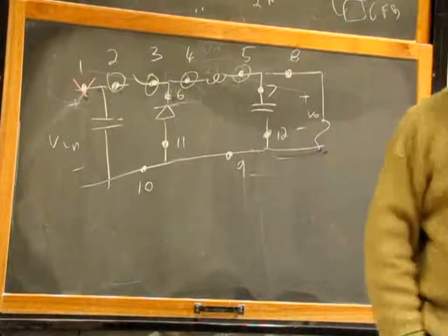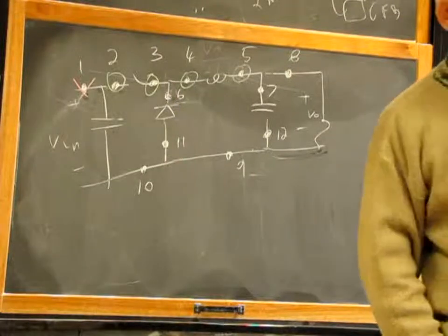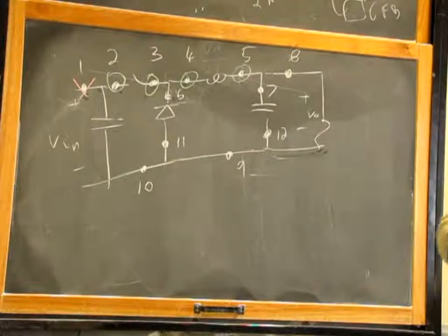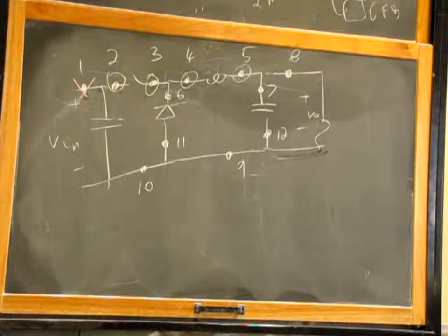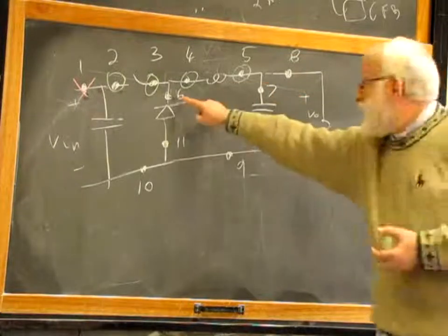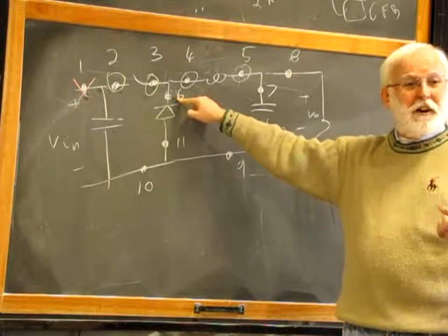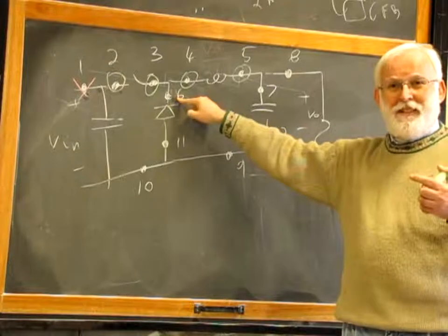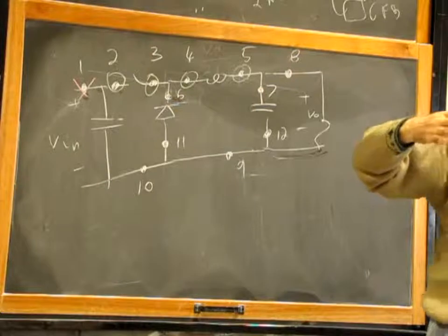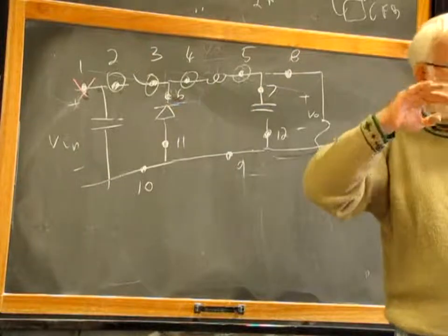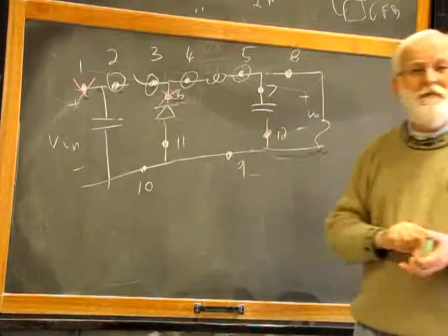It's like that guy who climbed a tree to trim it, and was sitting on a branch and was cutting the branch between himself and the stem. Here you have the peak current at the beginning of T off. But in order to start T off, you have to measure the peak current. So if you go over here, there is the peak current, but not at the right moment, because you need the peak current during T on to measure during T on. And during T on, here current is 0. So this is no.